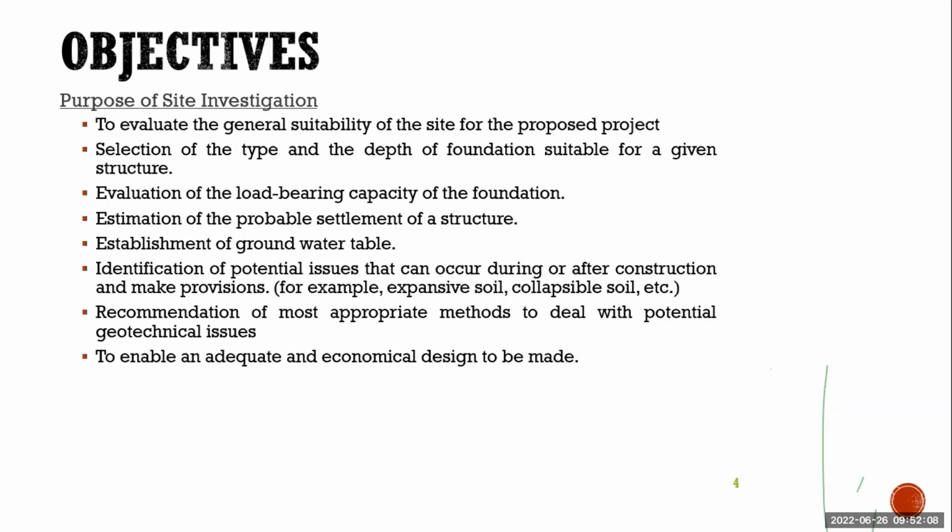And also, what is the groundwater table in this particular region? The groundwater table is very important, because if the groundwater is deep, no problem. If the groundwater is very shallow, or above the foundation, then it can reduce the bearing capacity tremendously. It can even reduce the bearing capacity of the particular soil by up to 50%. So it can affect the bearing capacity. That's why the groundwater table is very important.